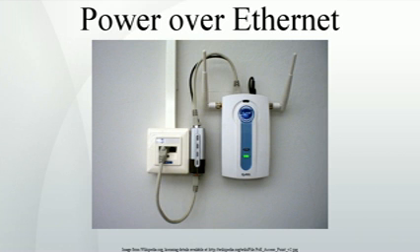Gigabit passive injectors use a transformer on the data pins to allow power and data to share the cable and is typically compatible with 802.3af Mode A. In the common passive PoE system, the injector does not communicate with the powered device to negotiate its wattage requirements, but merely supplies power at all times. Passive mid-span injectors up to 12 ports simplify installations.